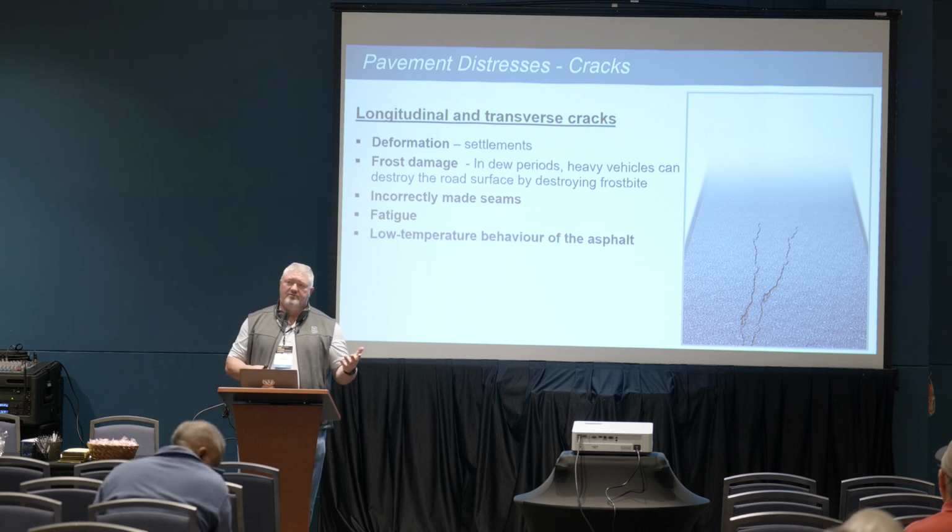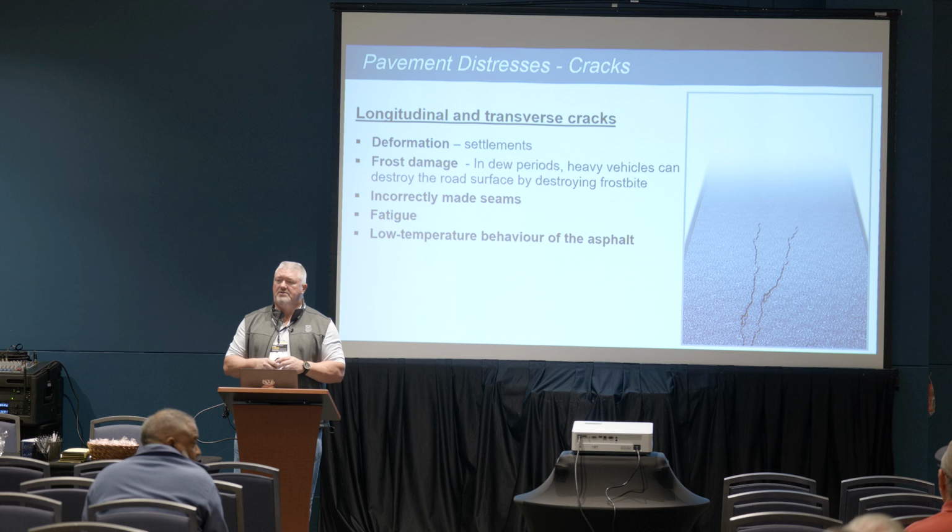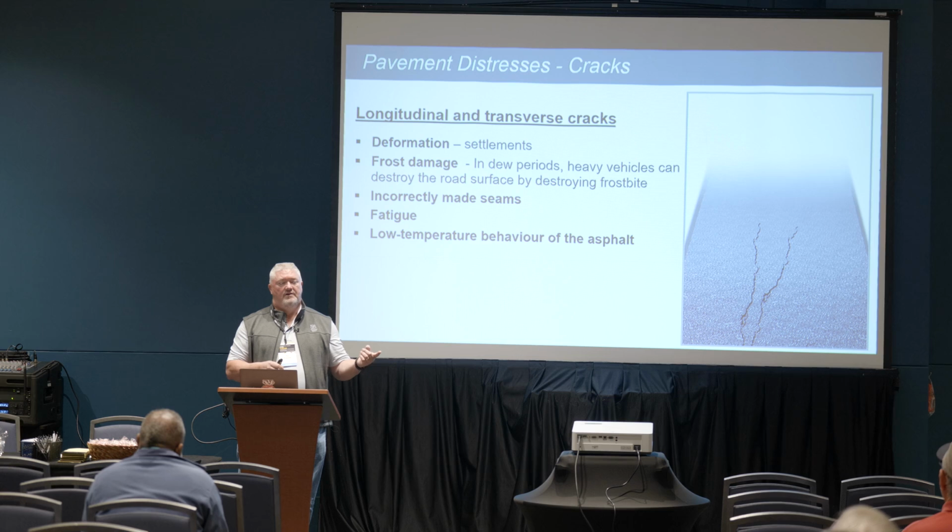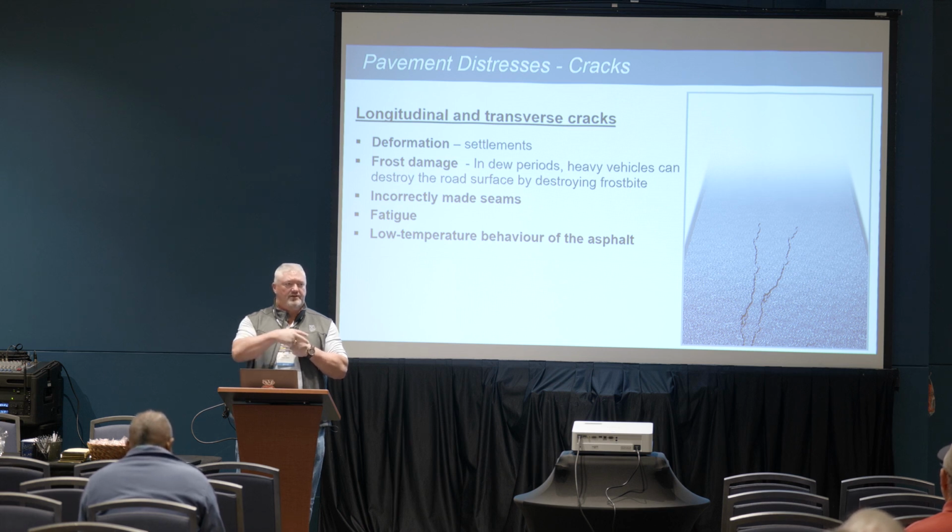Low temperature behavior, this is more of the tender mixes. A couple things cause tender mixes. The biggest thing is not getting the moisture out at the plant. If we got moisture still in that rock and we coat it with oil, that rock is hot, it wants to get rid of that water. Well, when it's trying to get outside of the rock, it gets trapped between the oil and the rock and creates this slip plane. And until that moisture gets evaporated outside, then it'll start bonding together.